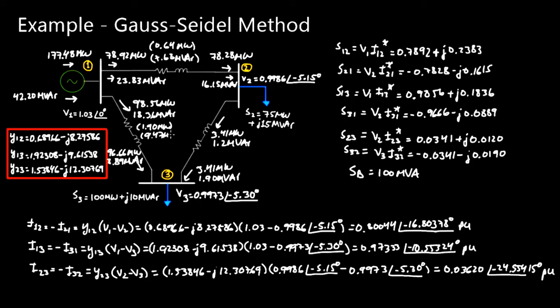And then lastly, on the transmission line 2 to 3, we have a loss of, basically these two numbers are equal to each other, so 3.41 and 3.41 megawatts. Now there's obviously going to be a loss in this transmission line, but I think just because of rounding errors, or rather we've approximated everything to 2 decimal places on a megawatt level. And so that's why it seems like there's no loss in there, but there's actually going to be a loss.